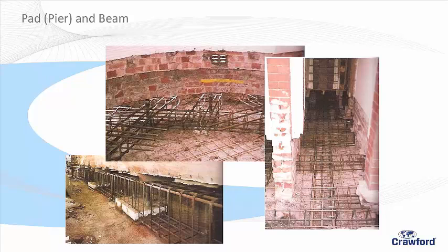And inside, on the flank wall, you would cast your pads, then you put your sacrificial stools in. Can you see them? They're just there under the reinforcement, and that's supporting the house. You can just see the sacrificial stool there. That's under the bay, by the way, inside someone's lounge. Obviously not a lounge anymore. And this is in the hallway. What you do is you cast the beam. Once it's cast, you cut the sacrificial stools. They just stay there. And then you dry pack.